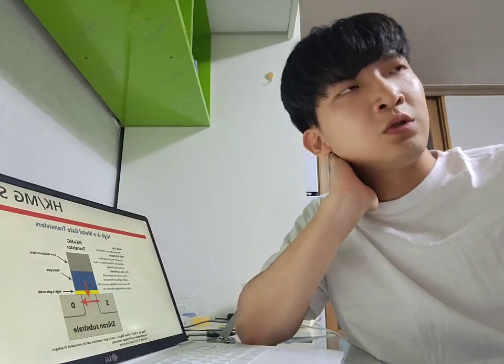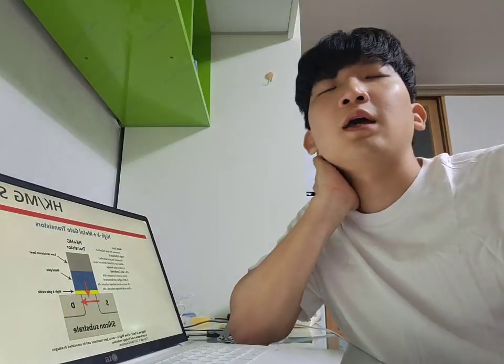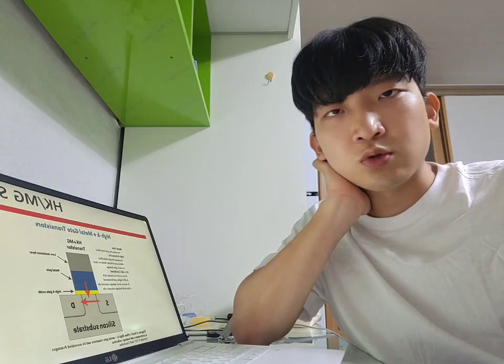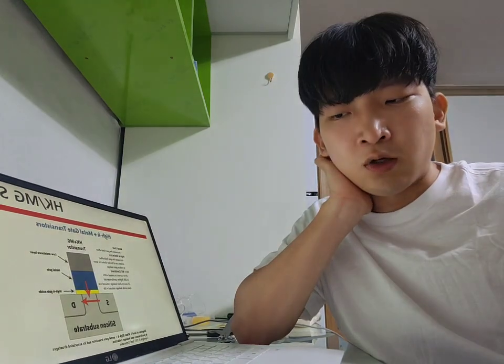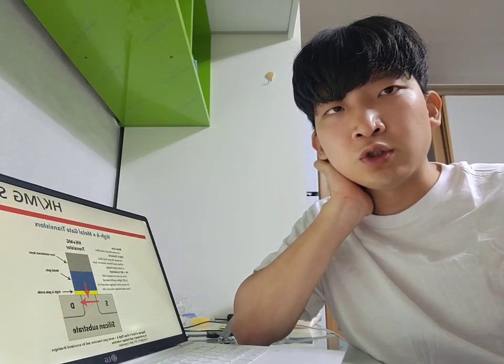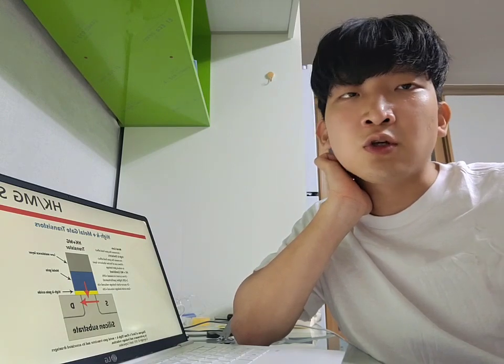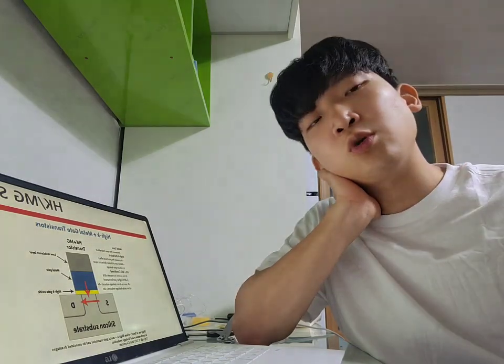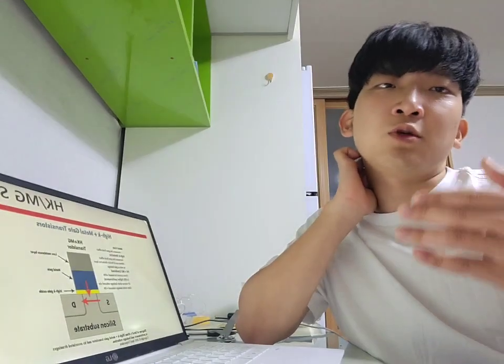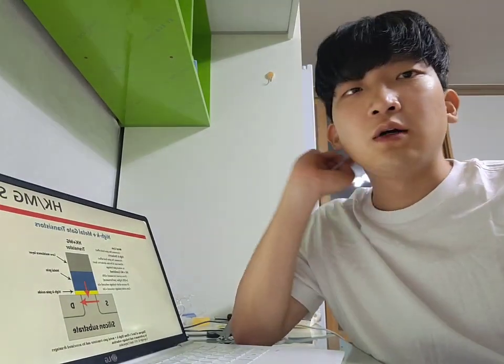Hi, this week we'll talk about some high-K material and some FinFETs. As we've learned before, we should increase the epsilon to get a good current. And so to do that we should increase the epsilon, and so we use some high K material, high K gate or high K material. To use some high K material, we should consider these things.